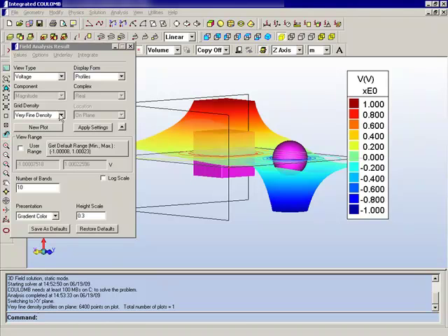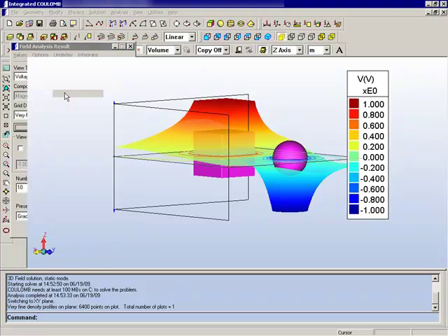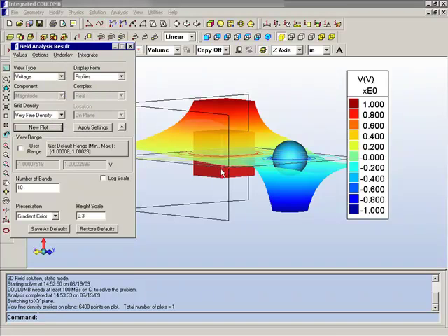One other aspect to the plots that you look at is the general background and underlays that you may be using, which aren't directly the plot but influence the overall impression. The plot that we've been looking at is coloring the geometry according to the boundary condition. It appears pink to indicate that voltages are applied. We can change the underlay to materials or media, and in this case we see red for the electrode that is assigned as copper and blue for the electrode that was assigned as aluminum.